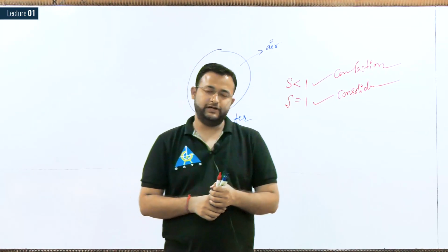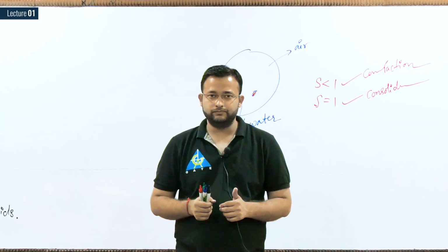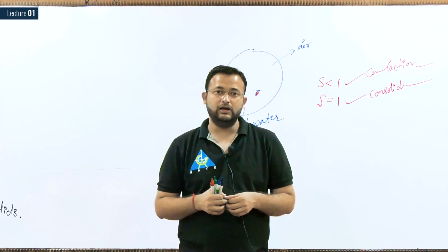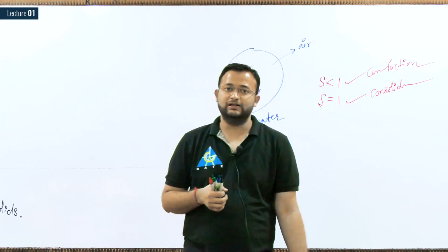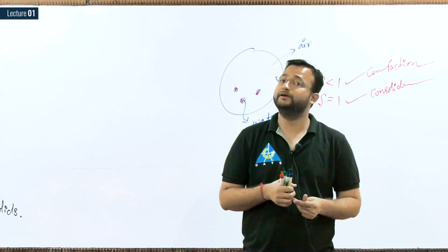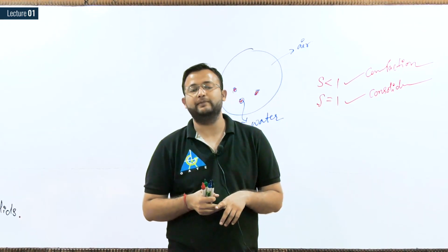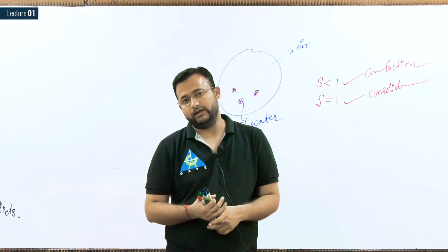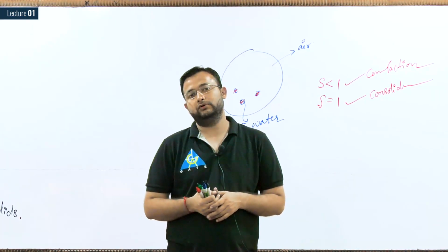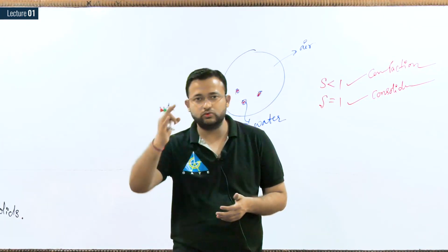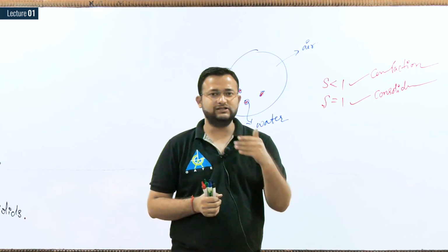But in the case of consolidation, we have to remove the water, and removing the water from the soil is a time taking process. It depends upon the permeability of the soil also. If the soil has less permeability, I mean to say if the soil is a fine grain soil, the permeability is very less, it takes a lot of time to remove the water from the soil, because water has to come out, it has to flow through the soil.